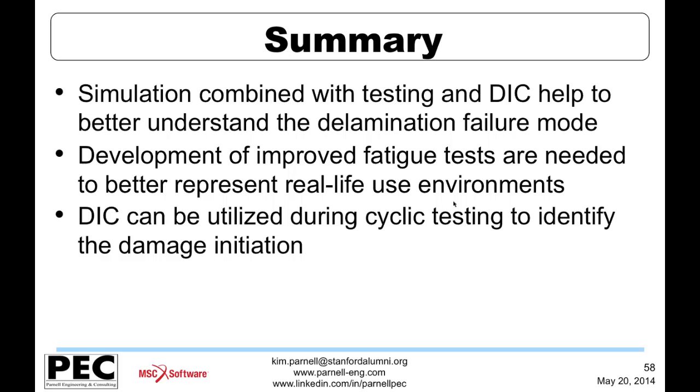We talked about fatigue testing of these types of components and some of the challenges in developing the right types of fatigue tests. And we also talked about utilizing DIC during not only slow static testing, but also through dynamic testing. So it can be utilized for things like fatigue testing or cyclic loading and that sort of thing.